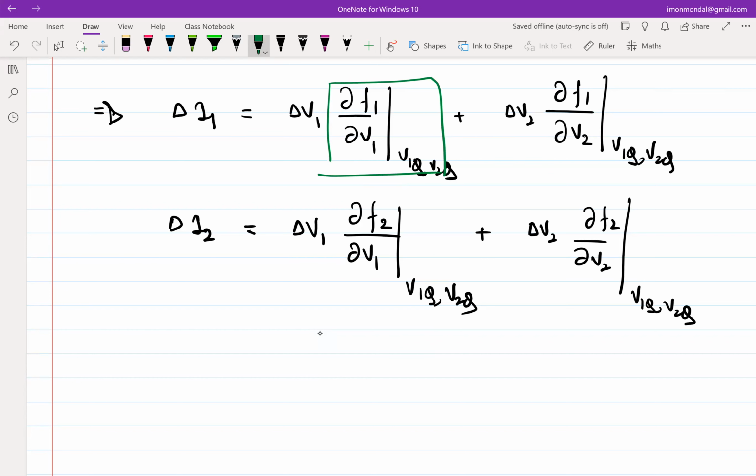All of these partials. Conductance, right? Its unit is 1 over I by V, it's conductance. So generally you have these matrices, right? Y matrix, Z matrix, H matrix, and so on. Multiple of them. Which one do you think is suitable? Y parameters, right? Y matrix.